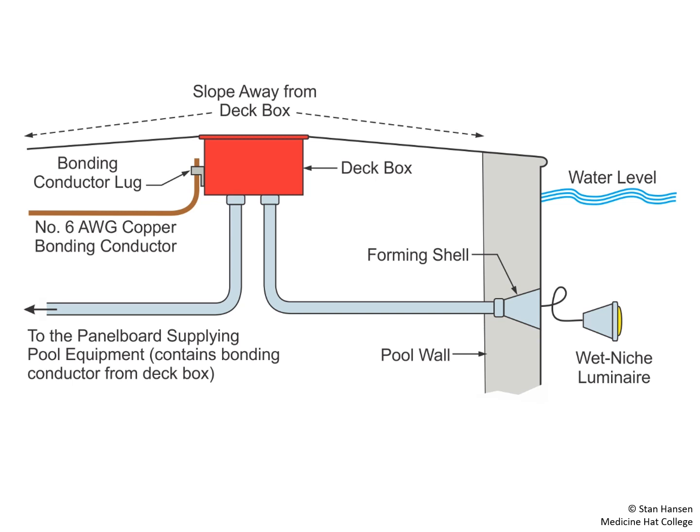Any raceways that come between the lighting forming shell inside the pool wall and the deck box need to be sealed to prevent any water from getting into the box. And the box needs to be located so it isn't an obstacle. So if you're walking along the deck itself, you will not trip and it does not become a hazard. We also make sure that there's a slope away from the deck box so any water will run away from it rather than towards it.